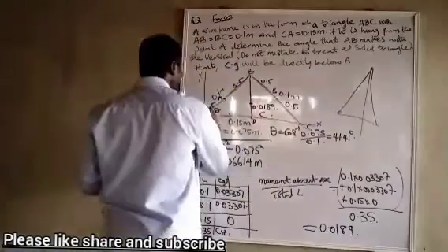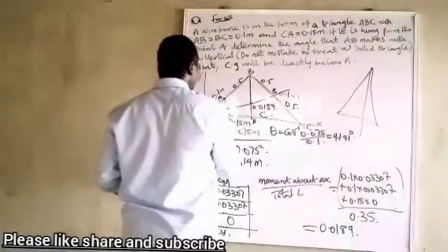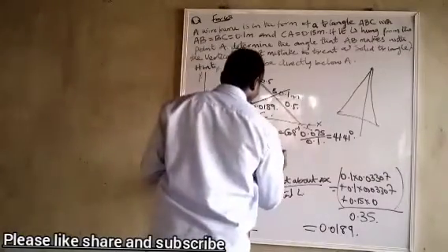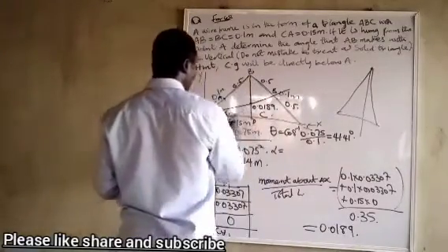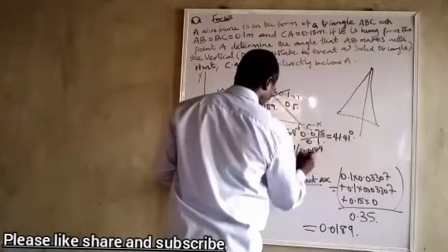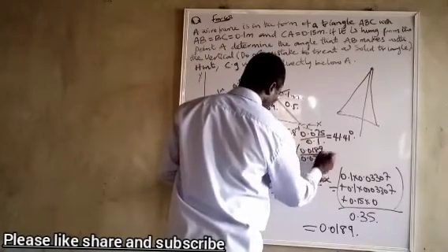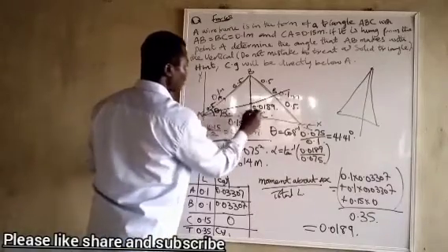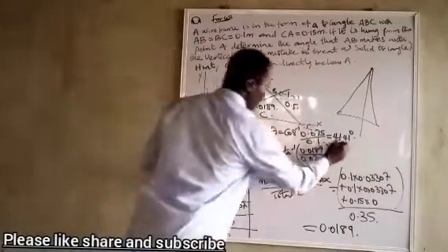Now, for a line that passes through the center of gravity, the angle made here, let's call that one alpha. So alpha is equal to, I know this place and I know this place, arctan 0.0189 over 0.075. Please, this is the triangle I'm considering. Let's make it AED.